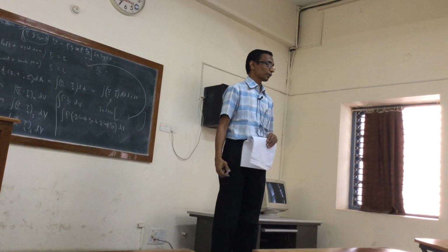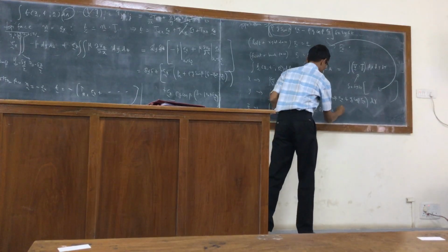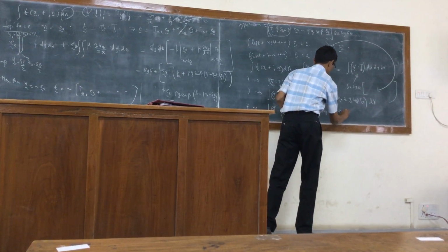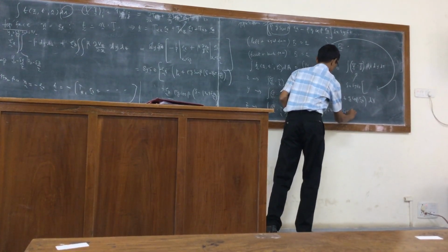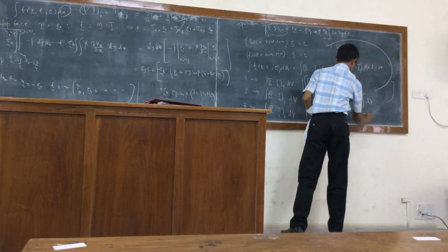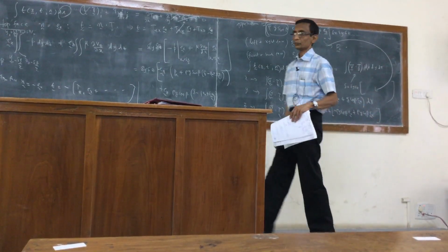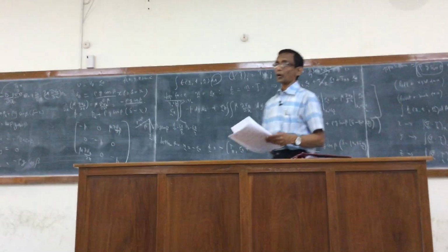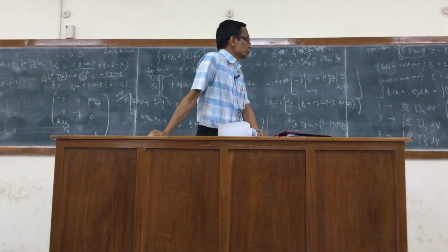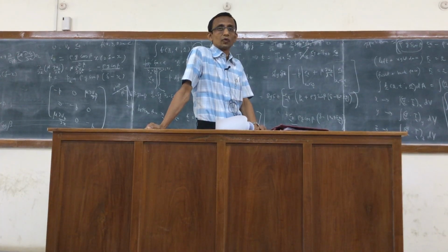The integral over volume is simply going to be the volume itself, delta x, delta y, delta z, times minus rho g sine beta Ex plus rho g cos beta Ez. So we see the body force is simply the negative of the contact force.